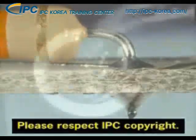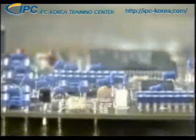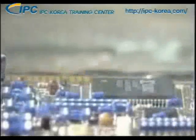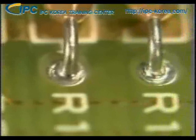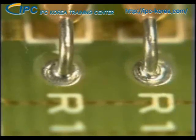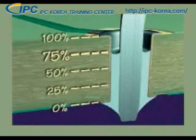One common variation of the fillet's shape is a slight dip into the through-hole before the fillet rises onto the lead. This condition is especially common on the component side of the board, as gravity can cause the solder to sag slightly into the hole as it solidifies. As long as the solder joint meets all the other requirements for acceptance, some amount of solder depression is allowed. A maximum total of 25% solder depression on either the component or solder side is permitted. This means that a minimum of 3/4 of the barrel must be filled with solder.